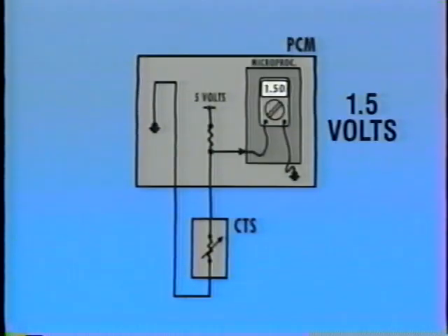The coolant temperature sensor uses a similar circuit, but instead of a potentiometer, this one uses a thermistor. That's a device which changes its internal resistance in response to temperature. As the resistance of the thermistor changes, the voltage drop across the sensor and the voltage appearing at the sensor's input change with it. Finally, there is a type of input that uses a pulsed or toggled voltage.